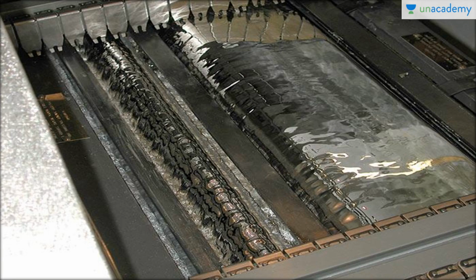This is wave soldering. Wave soldering has become a very popular approach nowadays for soldering through-hole components on printed circuit boards. This method uses a tank which is filled with molten solder. The solder is pumped and it flows. Its flow forms a wave of a predetermined height. The printed circuit boards pass over the wave, touching it with their lower sides. You can see this is wave 1 and wave 2, and this is how the whole thing flows.